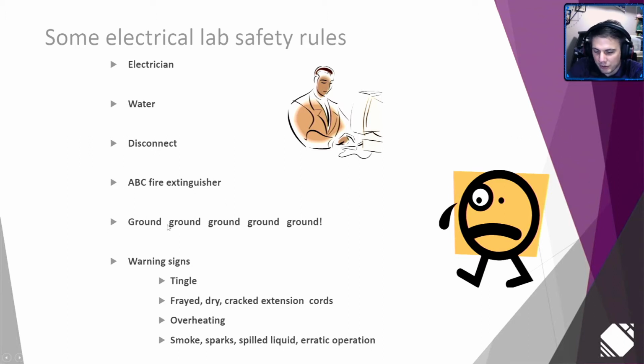And then ground. You have to have a clean connection to earth. It's explained in the electrical code very clearly how that needs to be developed. If you've ever been around something as straightforward as a home construction, you'll see bare copper conductor tossed in the trench around the outside of the building. It doesn't encircle the building, but it goes for a good 10 feet near the incoming service, and then that ground is brought in and grounded to a ground bar inside of your electrical panel in every home.